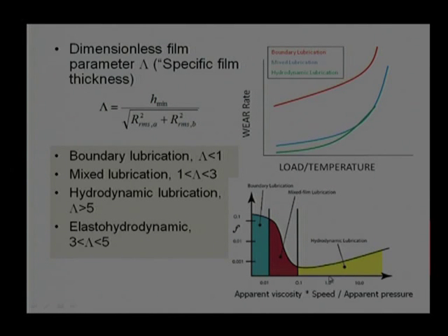That means, if a component was under hydrodynamic lubrication, it slowly moves towards the left-hand side, it will see the red color portion, and then if still higher load is applied or temperature increased, it will turn into the boundary lubrication mechanism. So every hydrodynamic lubrication mechanism, if subjected to higher or severe load, will turn into mixed lubrication or boundary lubrication mechanism.